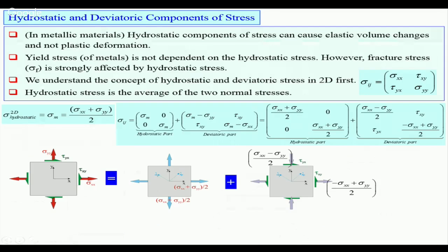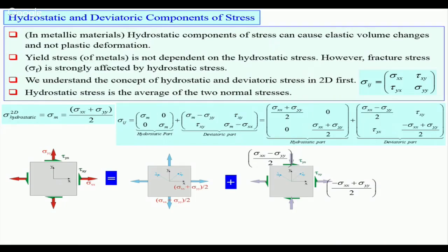Now, as I told you, deformation of a solid can be accompanied by change in volume and change in shape. So if we write down the equations of the normal principal stresses acting on a body, we will have two basic parts. One is the hydrostatic part, another is the deviatoric part.